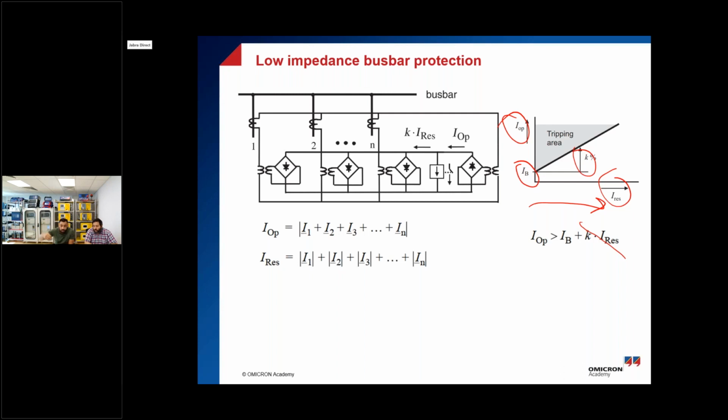As the loading increases, the CT ratio error will increase, and CT saturation may also have an effect, so the operating current will increase to avoid that. We can test this with the operating characteristic test module, as well as with advanced differential. That is our part from the Test Universe that we have.